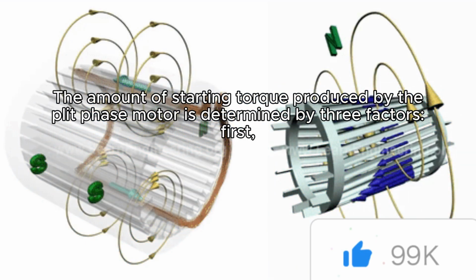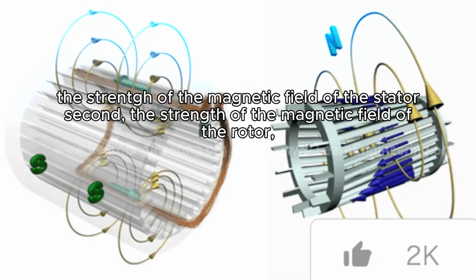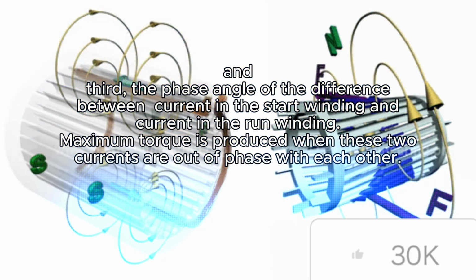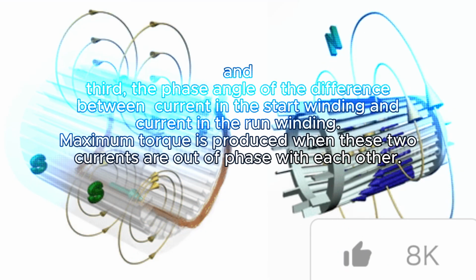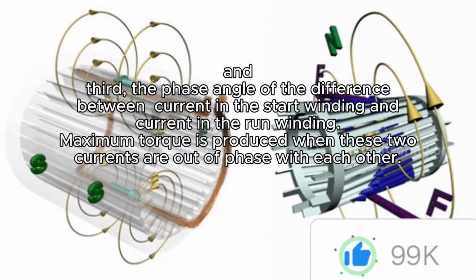The amount of starting torque produced by the split-phase motor is determined by three factors. First, the strength of the magnetic field of the stator. Second, the strength of the magnetic field of the rotor. And third, the phase angle difference between current in the start winding and current in the run winding. Maximum torque is produced when these two currents are 90 degrees out of phase with each other.